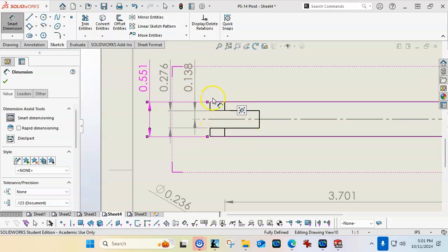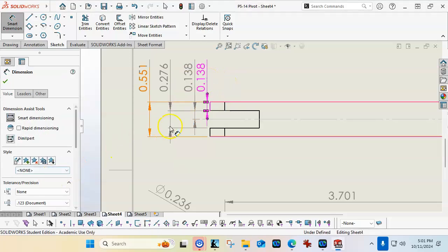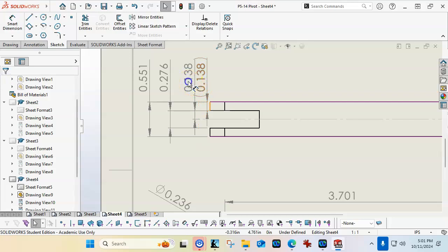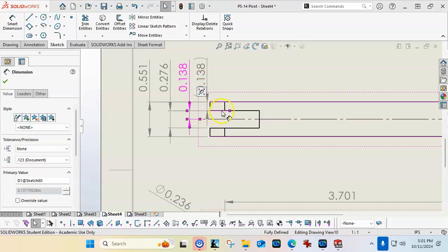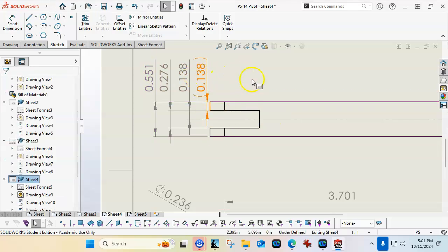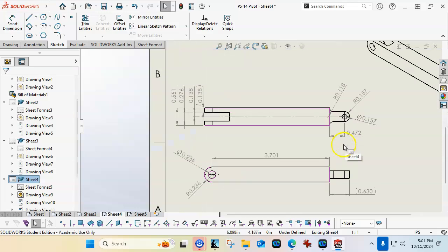So do one, and I think we'd probably do a reference dimension again for that side because, well, I still need to do the stack up, but what is going to control this, or what is more critical, is the slot width and the overall. And if this changes position, then this number would be the one that I would want to shift.